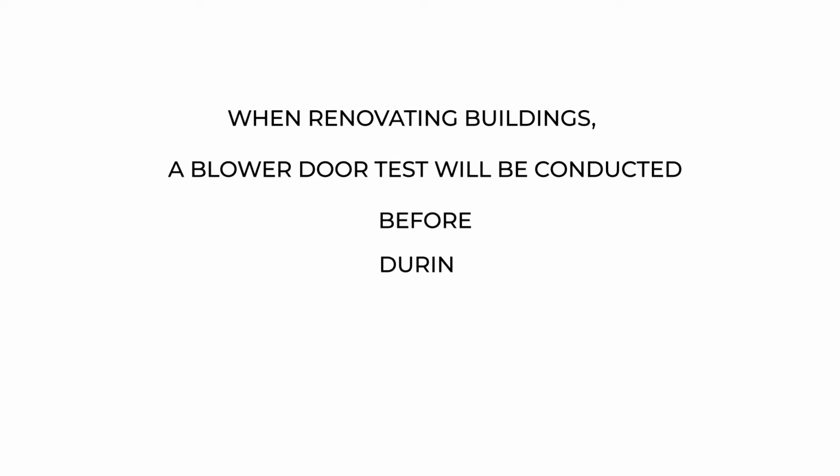When renovating buildings, it is important to understand how leaky a building is, because major energy savings can be seen when increasing the air tightness. Therefore, a blower door test will be conducted before, during, and after renovation.